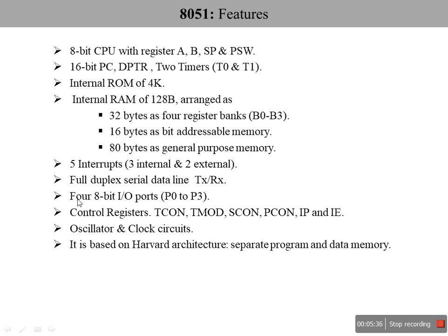In addition to these, we have ports. 8051 has 4 ports, and each port is 8-bit wide. Meaning of saying 8-bit wide is each port has 8 pins. They are named P0 to P3.